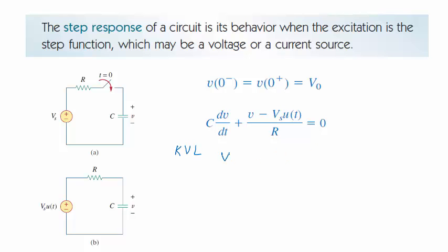And when you do that, you have the voltage source right there. And we know it's voltage source U of t, but the voltage source equals this resistor voltage drop plus this voltage drop here, right? So it equals IR plus the voltage drop of the capacitor. So remember, we're always seeking to know what this voltage of the capacitor is, which, keep in mind, is a function of time. Now this is a loop circuit. There is one and only one current in the circuit: I in the capacitor is the same as I in the resistor is the same as I everywhere.